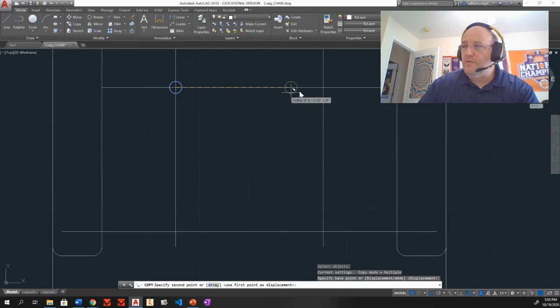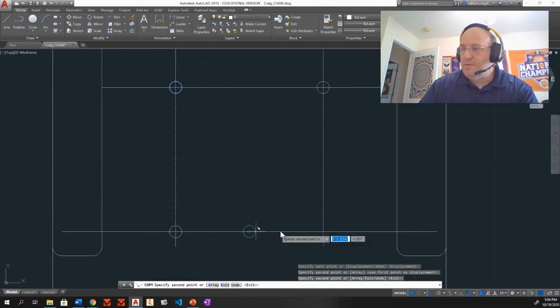And then what I can do is just drag over, and once I get off onto this intersection, it is perpendicular. You can see I had that little green symbol there. Say, hey, I'm at a perpendicular intersection. So that's good. I'll click. Let's drag down. And hey, look, because I'm working off of the same one here. Drag down, and look, I'm at perpendicular. That works. Actually, I was going to press escape. We're going to do this one again.